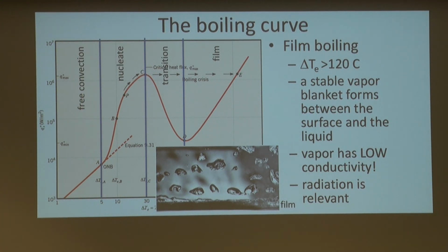You see in this image there that the bottom is the solid, then you have bubbles on top, and then in between the very bottom, that is the solid, and the bubbles, you see this film, right? And this film is relatively insulating. But of course, if you go crazy with the temperature, you're going to start conducting heat, but just by brute force.